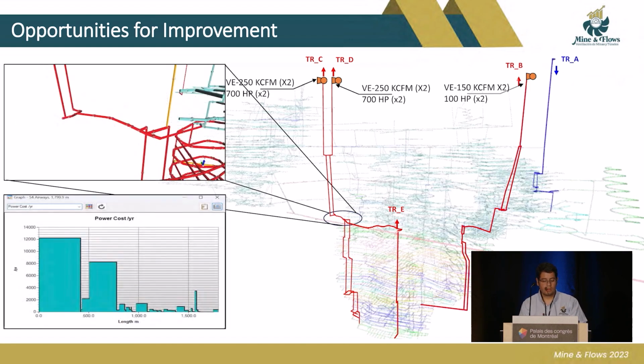Following the geomechanical considerations, a resizing of the bottleneck airway is proposed to allow a reduction in the power consumption generated by this segment of the circuit. By using the linear statistics tool from Ventsim, we could verify the power consumption reduction and the corresponding economic benefits.